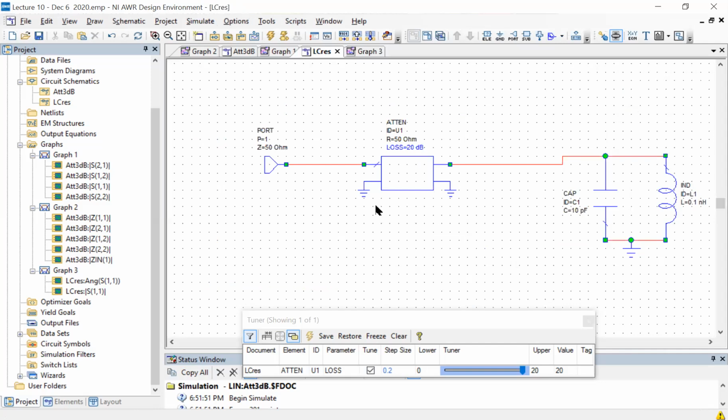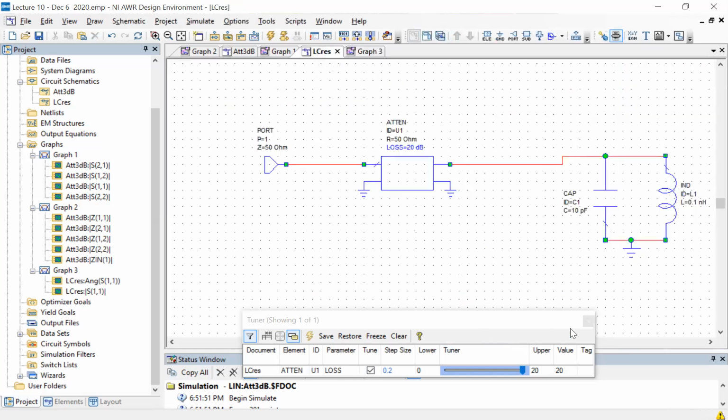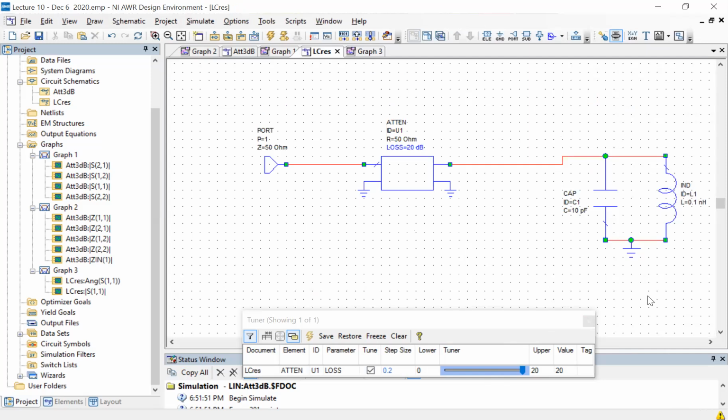It might just look like a 50 ohm resistor, except for this phase response, which is going to be very difficult in practice to see because of the signal to noise ratio. However, what is more problematic in interpreting is that you really don't know. In this case, because it was a simple LC oscillator, you sort of knew that its reflection coefficient in magnitude is always unity.